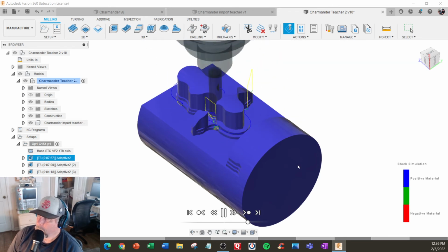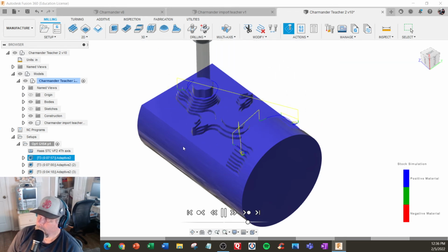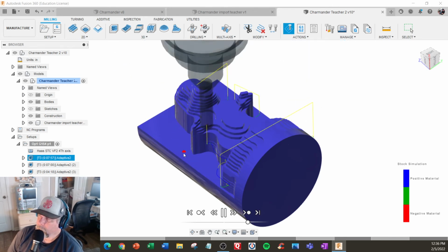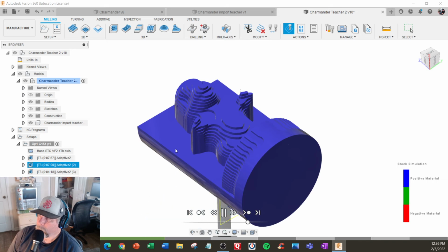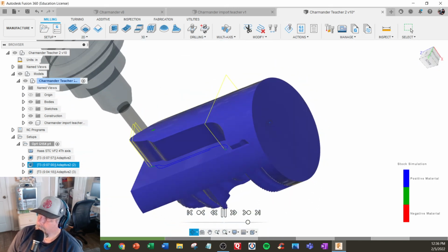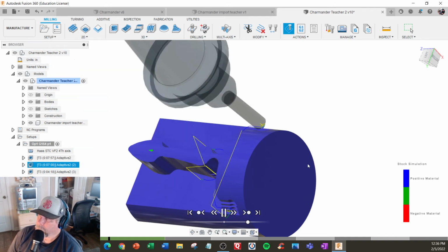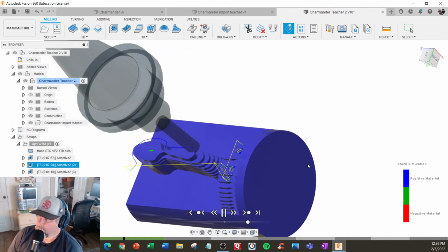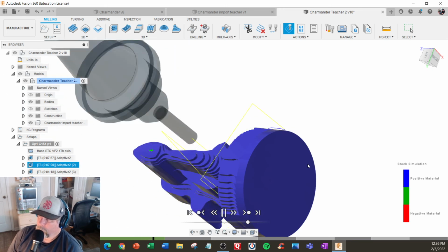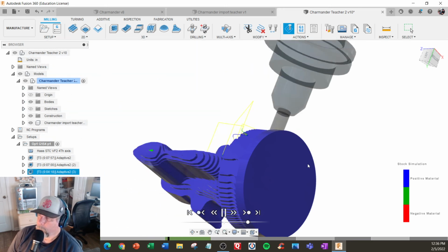Cut. We make sure we didn't want to cut around the back because that's where we're holding it. We had to build a barrier in adaptive in order to keep it from going there. And actually, you learn stuff from other CAD CAM. I actually learned that in Mastercam personally, how to create boundaries, because the OptiRough is kind of how that's driven. Where you put your fence.